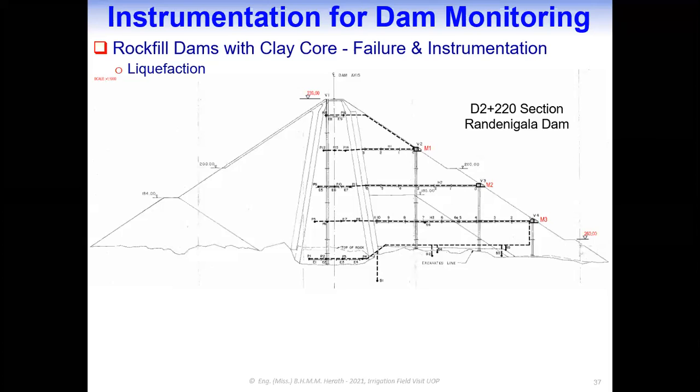As I have mentioned earlier, all possible failure modes stated for the concrete face rockfill dam are applicable for this clay core rockfill dam also. However, in addition, the liquefaction failure mode also could be considered.